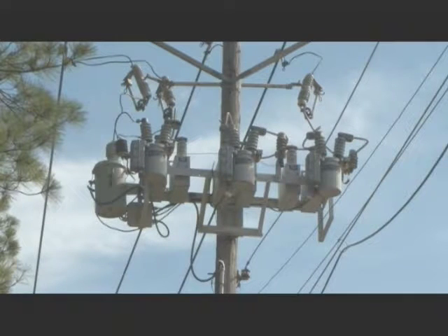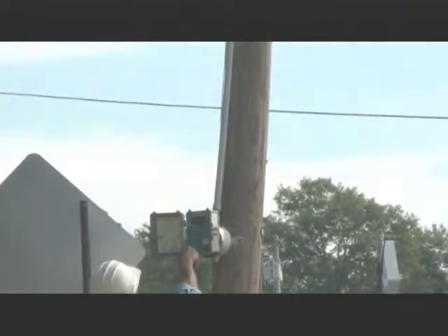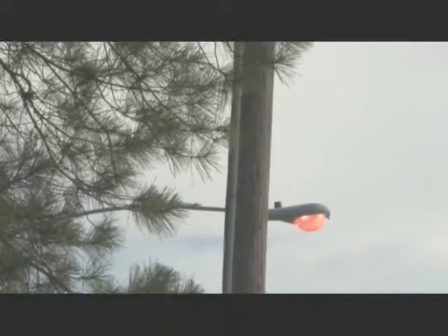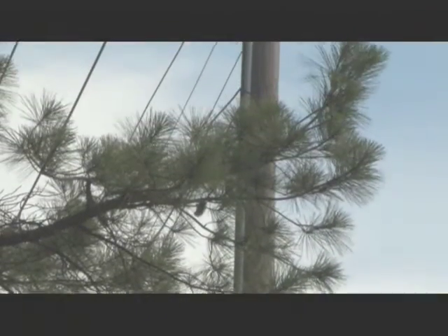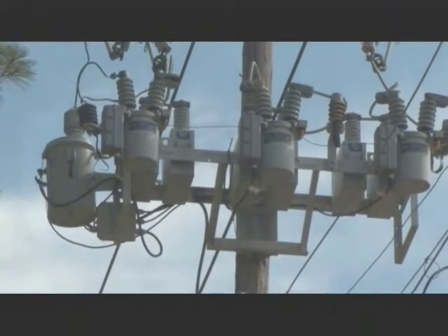Many capacitor banks, like this one, are switched banks, designed to be turned off and on rather than be online all the time. This capacitor bank uses a control mechanism located in a box lower on the pole to automatically switch the capacitor bank by opening and closing oil switches. The control mechanism is powered from a source of secondary power.